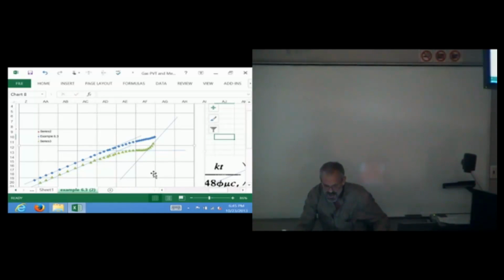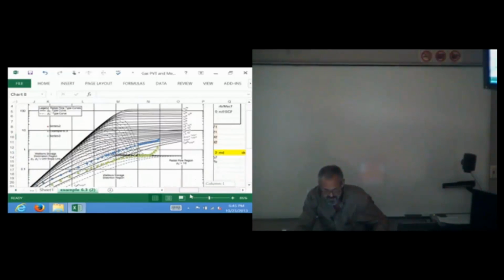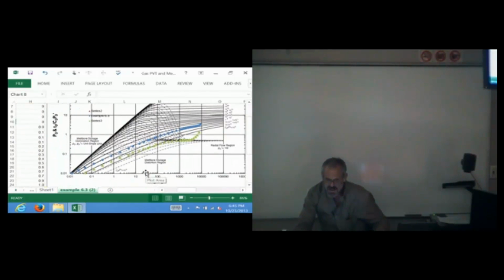And notice when I come back to my type curve that we have this telescoping thing of lines between the P sub d and the T sub d, and we don't ever have parallel lines between our derivative and our dimensionless pressure function. So there's no radial skin storage data before my radial data.